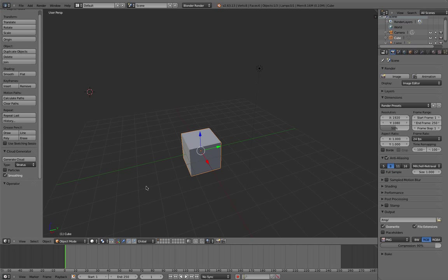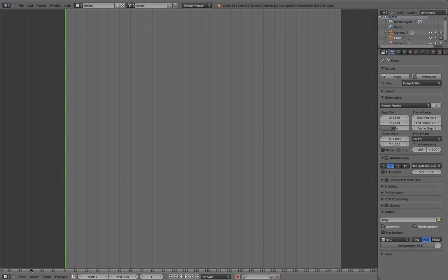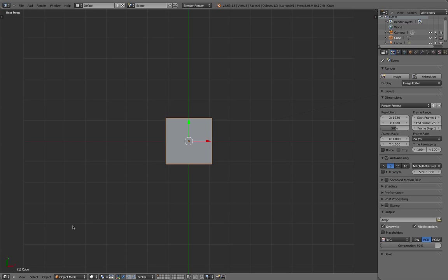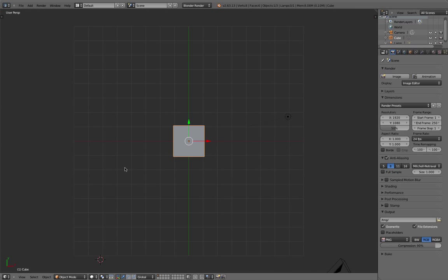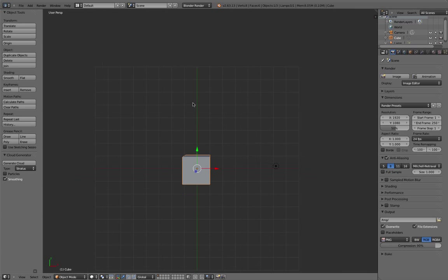The second thing I'm going to do here is click and hold in the top right hand corner of this window and drag upwards to merge those two windows, change that back to 3D view, and press T to get back our object tools, just because we're not going to be working with animation today, and it gives us a slightly bigger workspace.